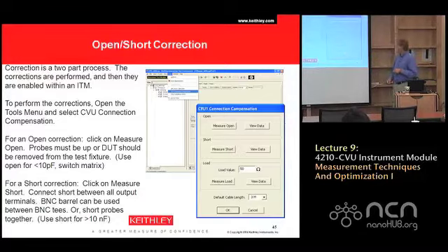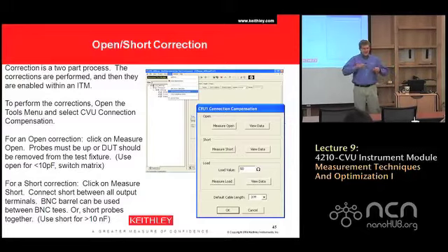In this particular menu, it sets up what we call the default cable length. It shows 3 meters here, but actually the default cable length is 1.5 meters. That's what comes with the instrument. The default cable length is the length that's automatically pre-programmed when you build a new test. So if you grab an empty test, a new ITM, and build a CV curve, it will pre-program in 1.5 meters for you.